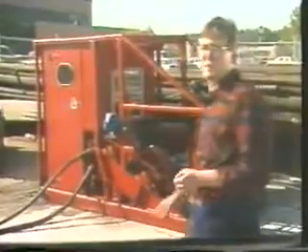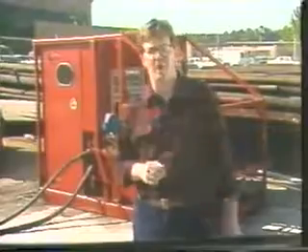Wireline operations permit repairs or revisions to the subsurface completion without the need for removal of the tubing and the expense that would entail, particularly at offshore locations. Wireline also permits routine data gathering and sampling activities and generally provides a means of physical contact between the operator and the distant subsurface. Here at the Baker Training Center test well, we see the equipment required for wireline.